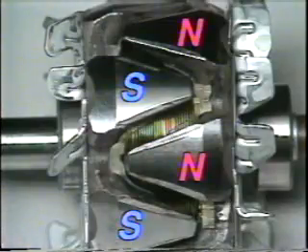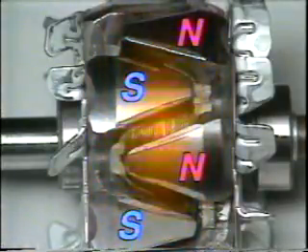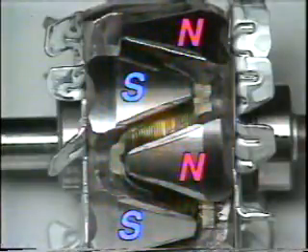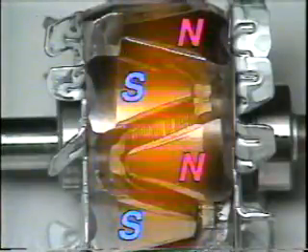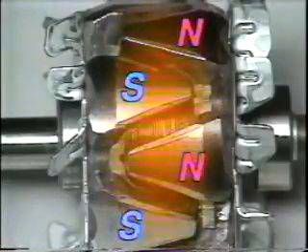When the current flows to the rotor coil through the slip rings, one of the cores becomes the north pole and the other becomes the south pole. That is to say, the rotor becomes an electromagnet. The strength of the magnetic field can be changed by varying the amount of electric current supplied to the rotor coil.